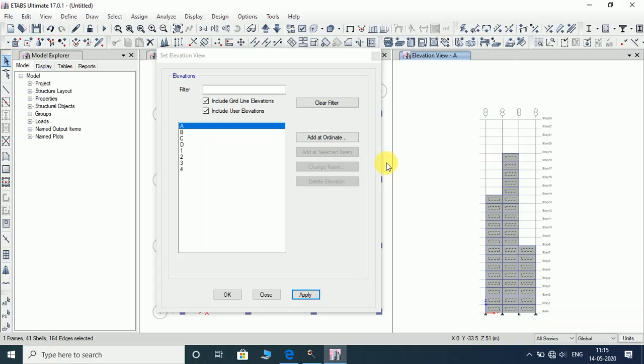When we see the code of IS 875, there in the plan it has been given A, B, C and D. Along the A side it has the coefficient of 0.8 windward coefficient. And how we check it? When we go for IS code, we first need to find out the total height of the structure, that is 23 into 3 meters, we get 69 meters. Width is 18 and length is also 18. So H by W ratio gives us 3.83.